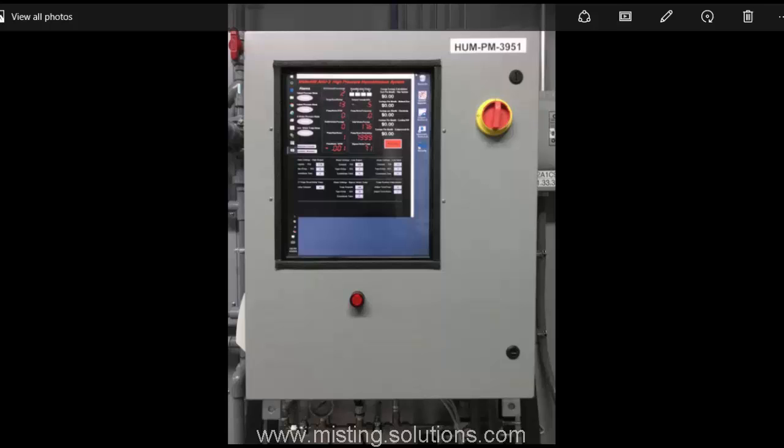First off, the actual output capacity, the demand required for humidification, is controlled by the building automation system, which is Johnson Controls. Johnson Controls sends a 0 to 10 volt DC signal to this control panel, which is requesting more or less humidification to the space to maintain the desired set point of 45%. You can consider that DC signal from 0 to 10 volts a 0 to 100% call for humidity or demand.